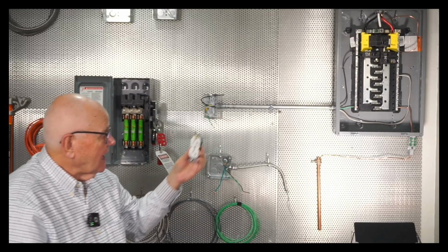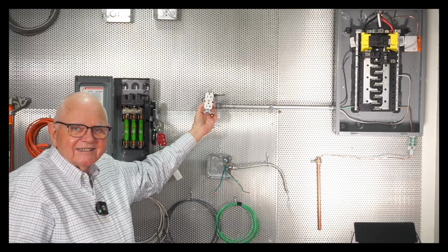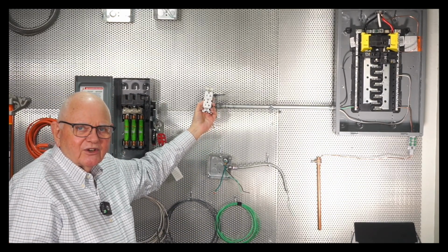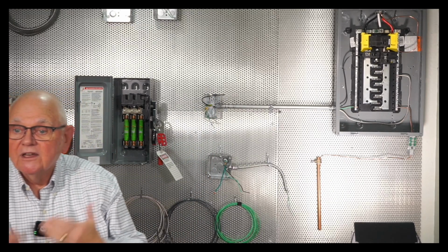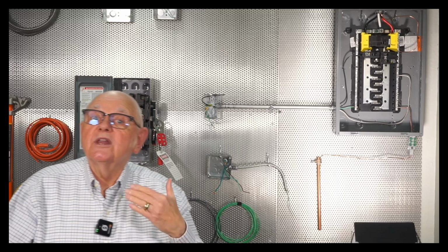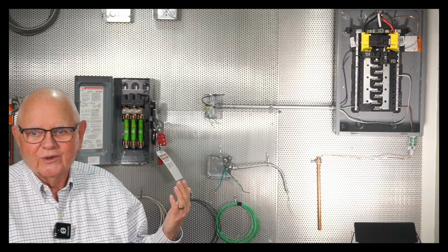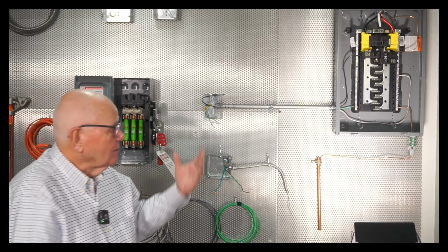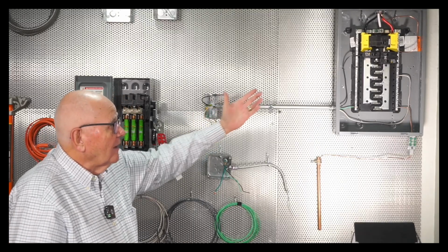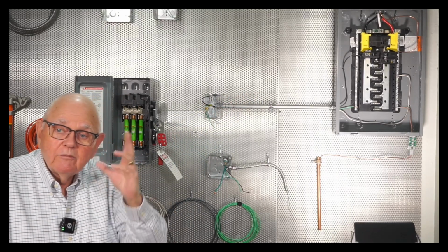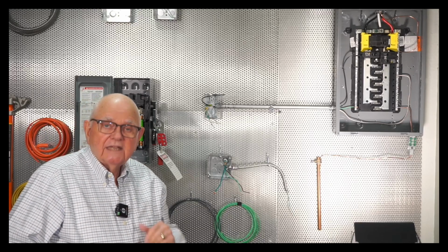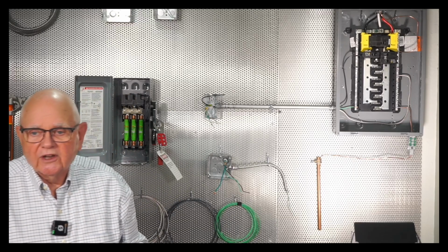They're all attached. The equipment grounded conductors on both of these receptacles are attached to that metal yoke. Now, by definition, if I just had one of these attached on this particular branch circuit, I could call that a general purpose branch circuit because I have two receptacles. Generally, we run a lot more than that, don't we? In fact, we might have some lighting coming off of that one branch circuit. We may have some general purpose receptacles. We might even have an appliance. It's still called a general purpose branch circuit.